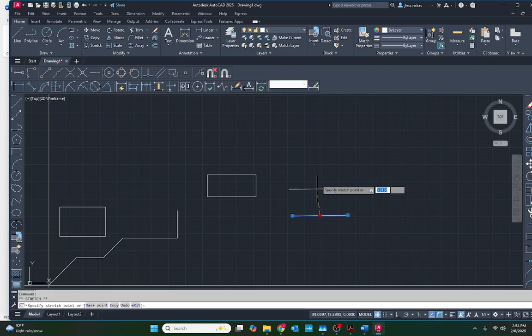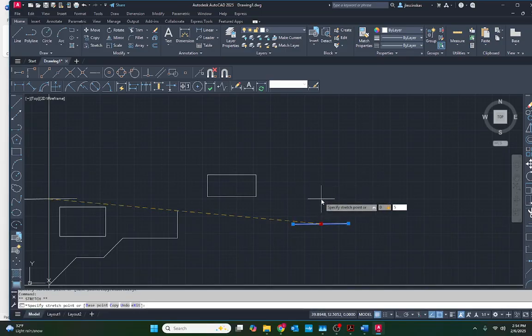And this is simply moving the line. Now, when I move the line, and by the way, we generally don't move lines like this. Typically, the way we'll move a line is we will move it, and then we'll actually type dimensions. So we might type 0, 5, which would move it up 5 units. In that case, I didn't do it, but I should have typed the @ just to reinforce that it's a relative move. So that will do a move.